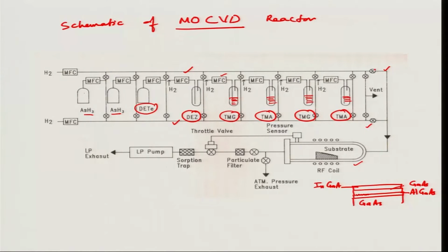So, the composition should change very abruptly, and that is why such a sophisticated reactor, such that you have a controlled flow all the time from the reactor and also to the vent. So, before you switch the chemistry or the composition, you start flowing the same composition to the vent first, okay, and then you switch to the line which is going to your reactor.